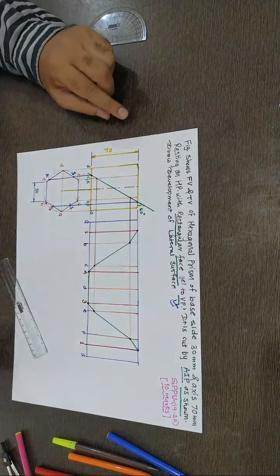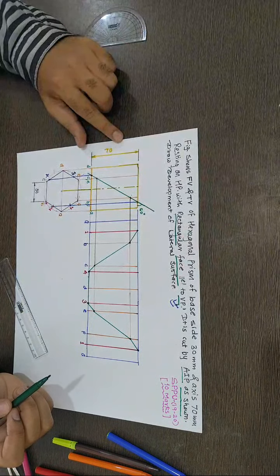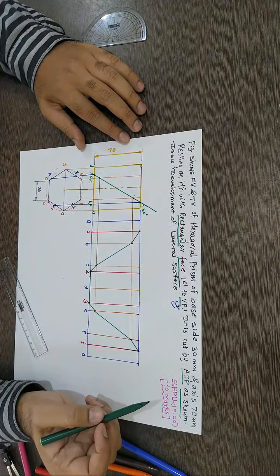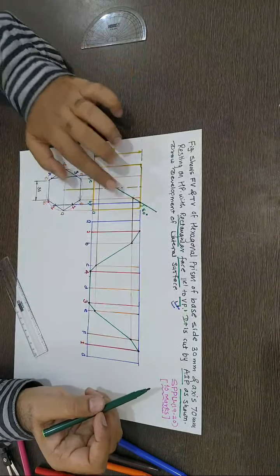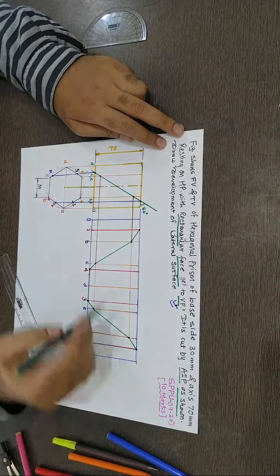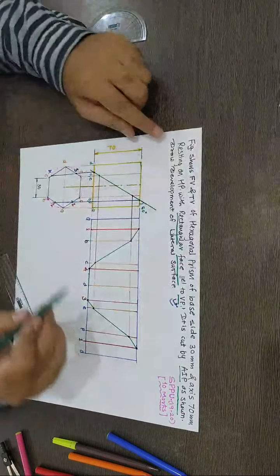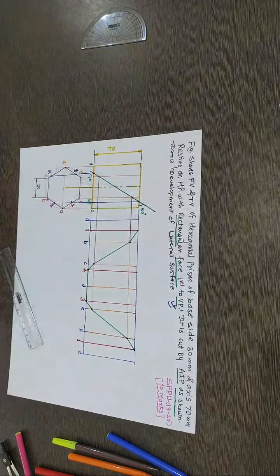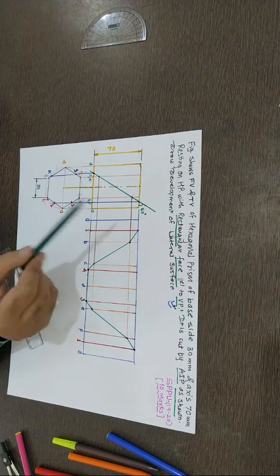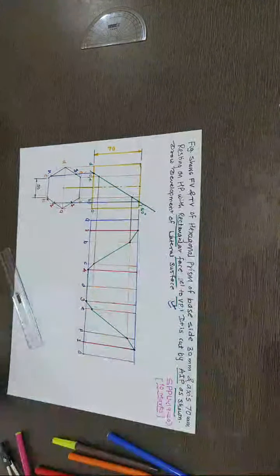So yes, this is what you can see when these are the given conditions, when you have a 30 by 70 prism with one face parallel. This is the angle, so the top face is here. This is the development obtained, which I have shown here by joining the lines. The only additional thing was when the cutting plane has an intersection with the top face and bottom face, or maybe any other one face, or if they give only a solid like this, how you can obtain the development.